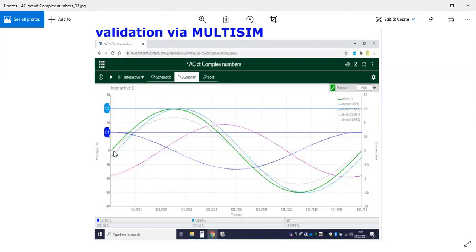If we want to look at the phase shift, what we can see here is the voltage crosses the 0 axis at time 0 here, and a little bit later the supply current crosses the 0 axis at this point here. There's a very small time difference, which is phase difference here, which is 90 degrees here, 180 degrees here. It's a very small phase angle. It's below 45 degrees. You're talking 10, 15 degrees here, just looking at it by eye. We can see that the supply current lags the voltage by a very small phase angle.